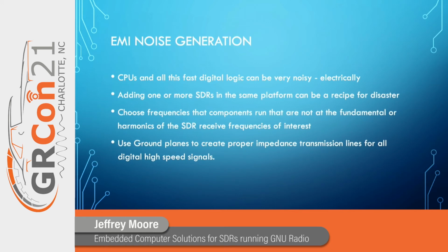EMI, electromagnetic interference noise generation. This is particularly important in SDR related applications, and it's important in all products because there is the FCC and other government regulation organizations that regulate how much EMI you can generate. But in an SDR world, because we have these highly sensitive radios, you do not want the noise that all this fancy digital circuitry generates to be picked up by these SDRs.